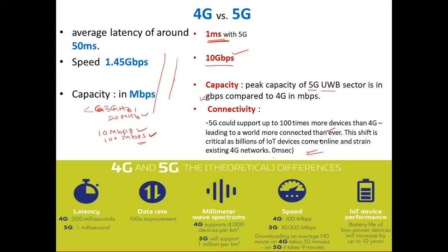And we know that existing wireless communications use sub 6 gigahertz frequencies, mainly due to the spectrum scarcity in lower frequency bands. That is the reason in 5G we go for millimeter waves. Starting from 3 gigahertz, it may go up to 300. Presently, they have planned up to 100 gigahertz, starting from 10 gigahertz: 28, 30, 60 around, and then 100, and below 100 somewhere like that. This was the present plan.